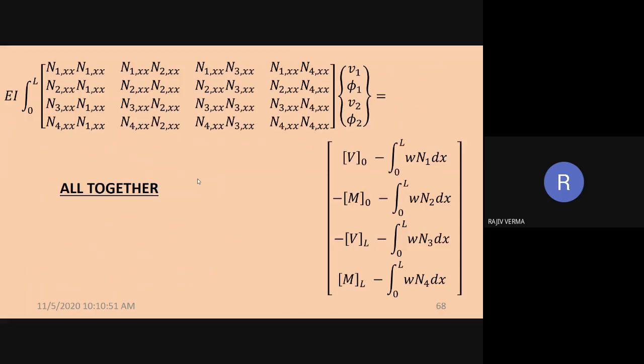We have taken an example of a bar element of a cantilever, which was divided into two elements and three nodes. So basically, we can refer to that particular solved example also for understanding how the stiffness matrix is going to be used for solving the unknown parameters.